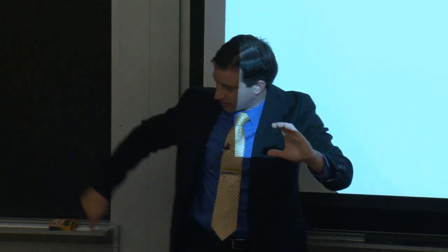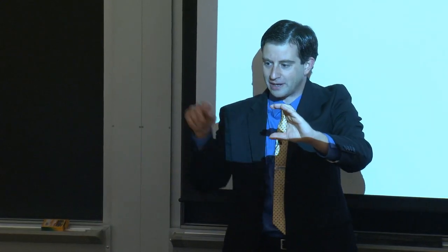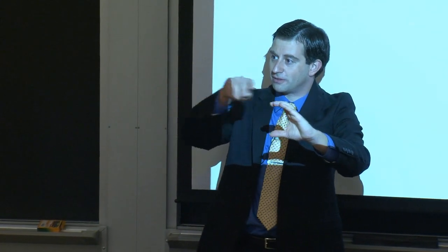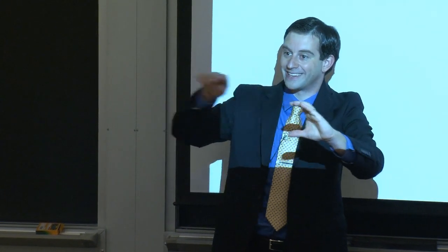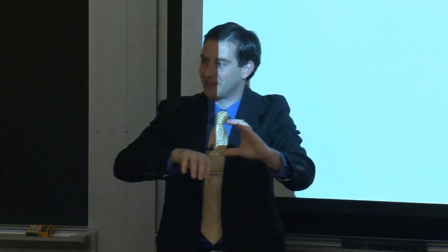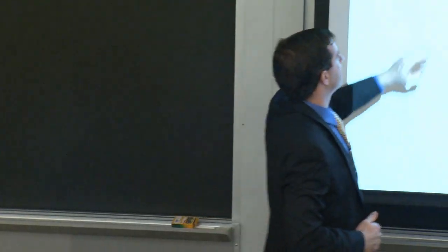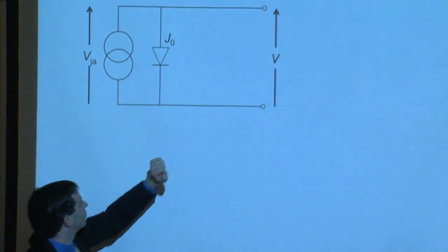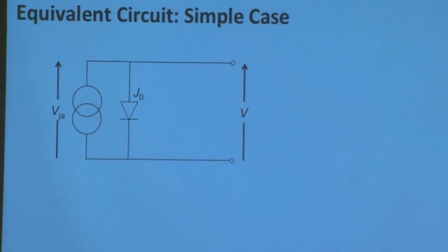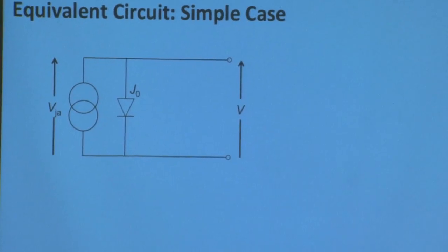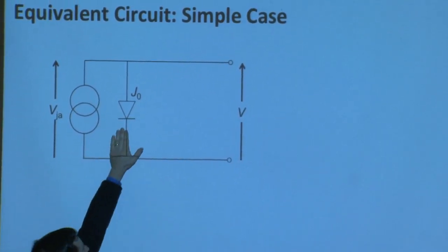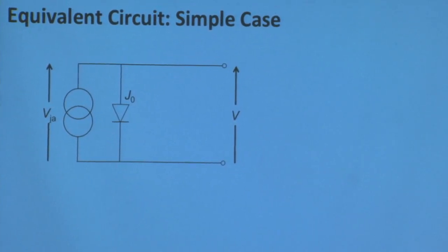Instead of powering the external load and coming back into the device through the back, leakage current would be the electrons going back up the barrier, right? Going back into the base of the device, the so-called diffusion current. So this is that diode right here representing the diffusion current, or in that particular case, in the ideal equivalent circuit diagram, this is representing the resistance to diffusion, if you will.